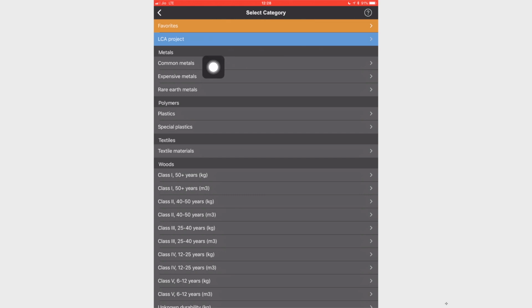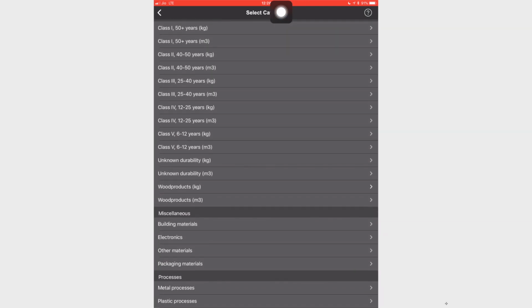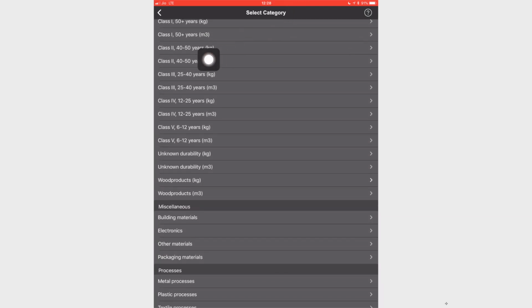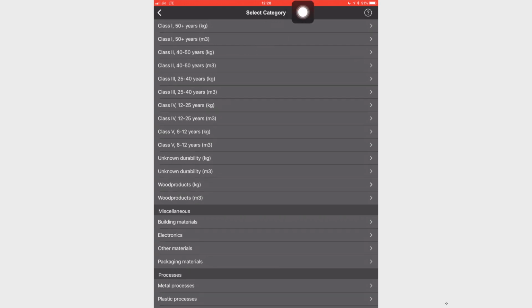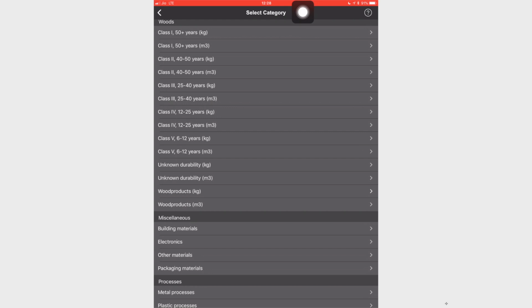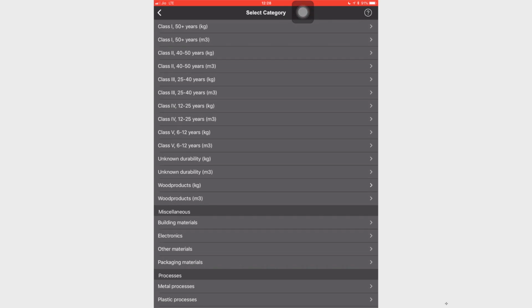Then because I have a film, I need the blow molding of PVC film, which is the approximation for the blow molding of LLDPE. So, I select that particular option, again press LCA, added to project. I have to do injection molding of my cap. So, I will select injection molding, again press LCA to add to the project.